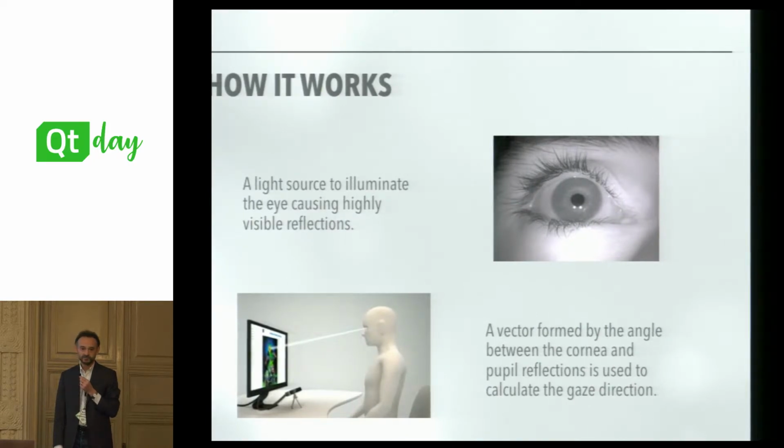It works in a really simple way. So the camera is just taking picture of the eyes, both eyes, because an eye tracker is capable of performing binocular tracking. And basically, it is an infrared camera, so this is a typical image of a device with two active infrared illuminators that you can see in the first image. They are called the glints, so the reflex, basically, of the infrared light into the cornea. Then there is a mathematical model that just tries to find out the center of the pupil, the position of the glints, the position of the head. So there is also an head pose estimation of the head of the person in front of the camera. And the device provides you with the vectors that simply tell the orientation of your gaze.